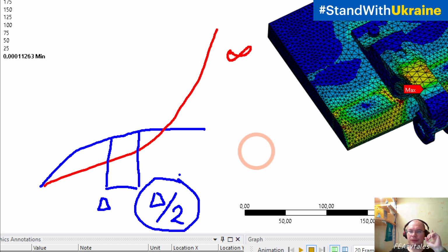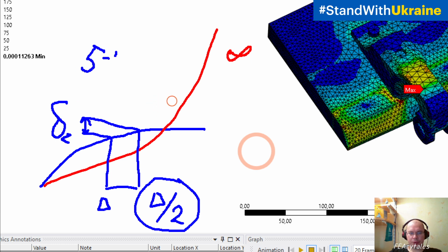If stress distribution, deformation distribution, temperature distribution, and so on are not changed, and if in objects which are not hotspots you have error less than you need, it's around 5 to 10% in most engineering calculations of difference, you can use those meshes even if you have much more difference in hotspots.